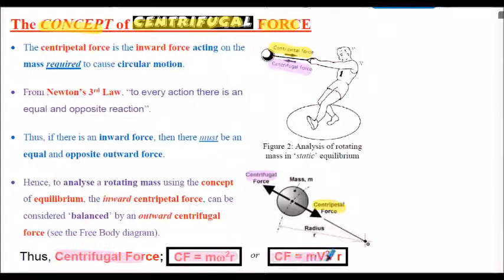And that's the only form we need to be aware of. All what I'm discussing here, it's really the mω²r formula you need to be aware of. I've just written it there in two formats, one in terms of linear velocity v and one in terms of angular velocity omega, but it's often this first one we need to use in the calculations. So that's just a bit of background. You'll see we'll use that formula later on to help us analyse these rotating masses that we're going to consider.